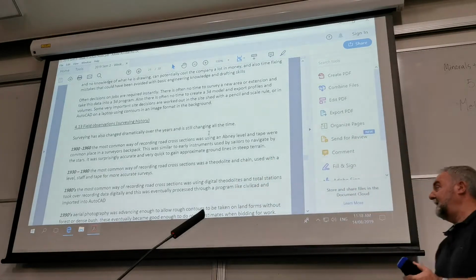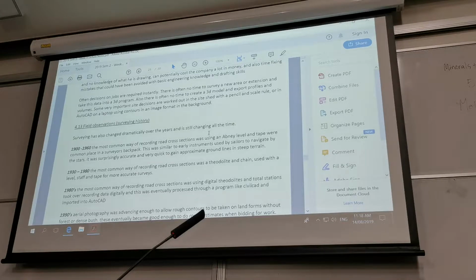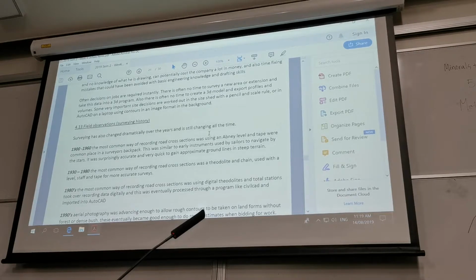So if you were walking over hills like this, it was very easy to survey that, even if it was covered in thick bush. Because you could start walking up here, you would put, both of you had a post about, I think it was 1.5 high, and you had a tape measure. And in essence, what you were doing was you were measuring that distance, 120.3, and you had an angle here which might be 3.5 degrees. And then you would take your next shot and move on, and so on and so forth.